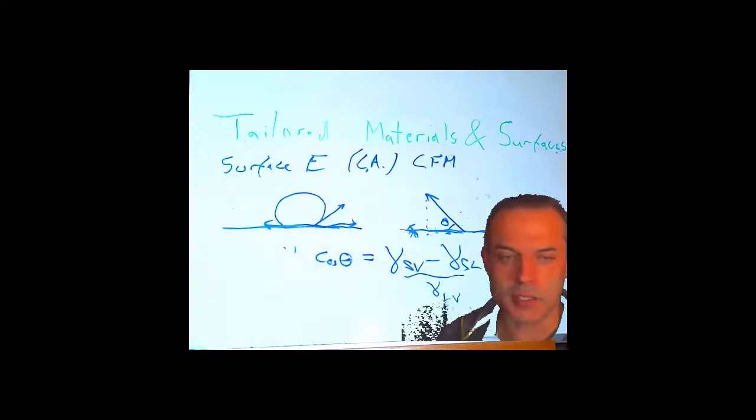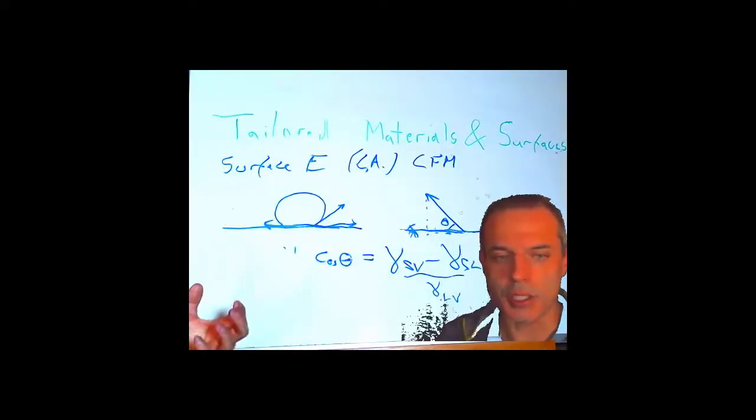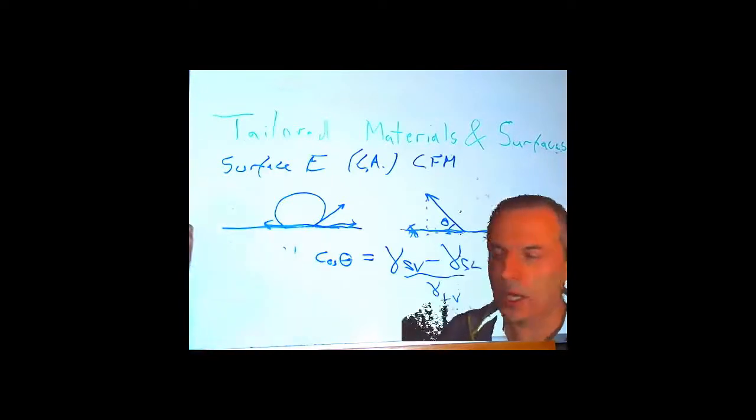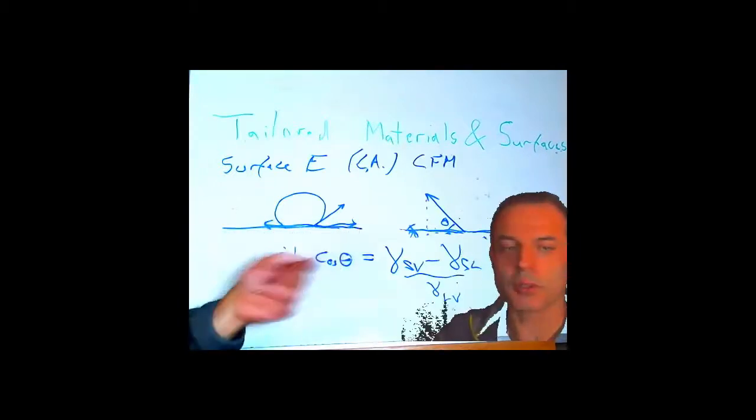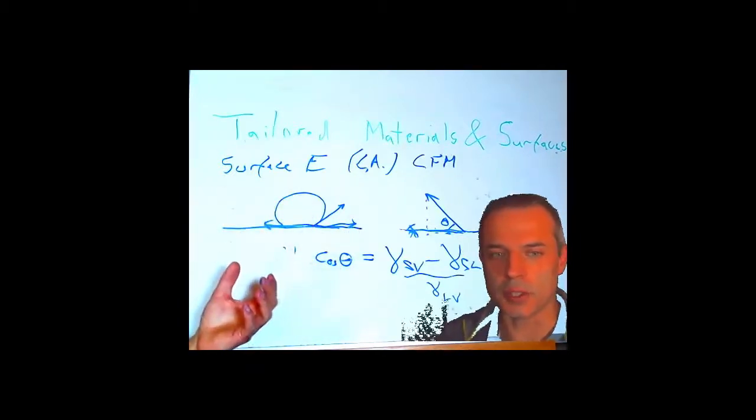It doesn't tell us the absolute values, but it tells us how energetic the surface is, and is often used as a quick measure. The more a drop spreads out, the higher the surface energy of the surface is. But getting the actual value out of it is not quite so easy.